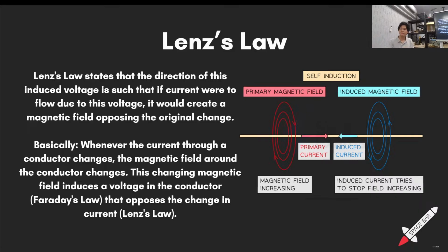Okay? So anything with inductance hates it when the current changes. It will produce a voltage that will fight against the changing current. A reverse voltage. Does it cancel out or it just? No, it doesn't cancel out. It's not strong enough, but it will fight against it a bit. A lot in some cases, depending on inductance. But never all the way. Will it ever go all the way? No, it can't. Not enough flux. Yeah, depends on time also.